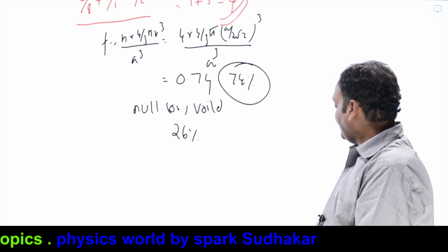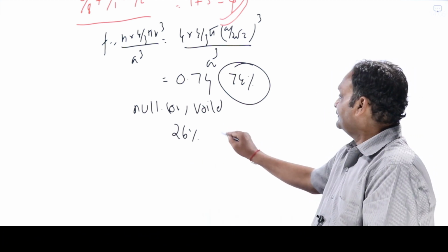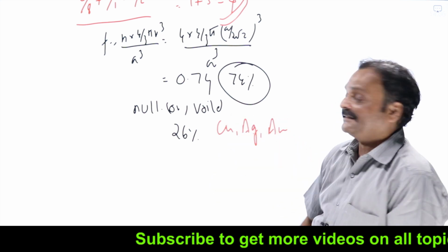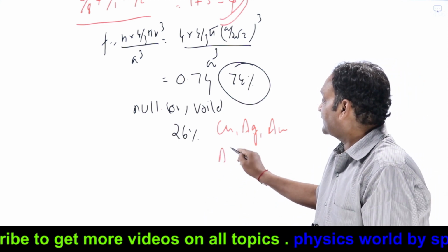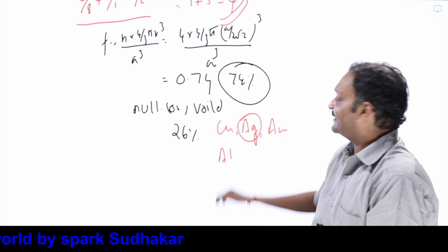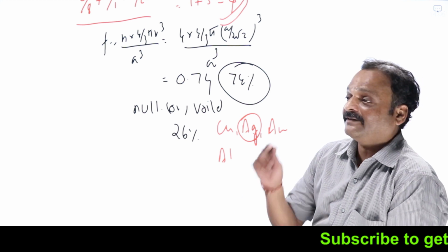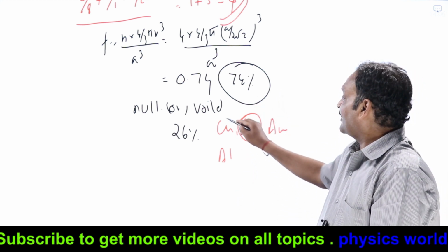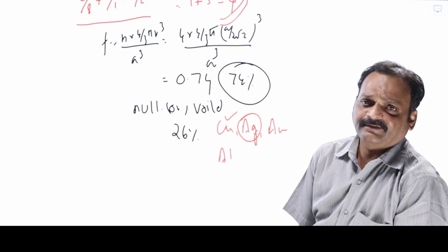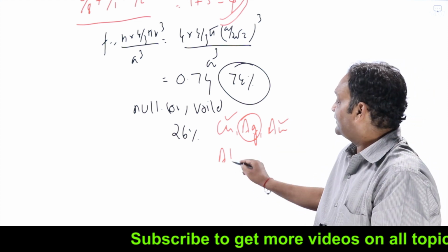Now what are the examples? All three noble metals, copper, silver, gold, crystallize in FCC structure. Aluminium crystallizes in FCC structure. For electrical engineering students, silver is the best electrical conductor and also the best thermal conductor. Next comes copper. Conductivity of copper is only 15% less than that of silver. Next best is gold, next best is aluminum.